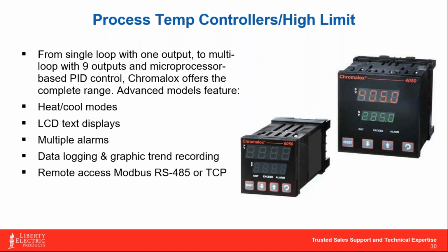A lot of the industry has moved towards HMI displays, using more of an integrated automation interface, and temperature controllers have dropped in popularity because there are just more advancements in technology and what you can do through a PLC interface, versus the customizations you can do with something like a DIN rail mounted process controller. But again, these are inexpensive, they're very effective, they wear like iron, and they're accurate.